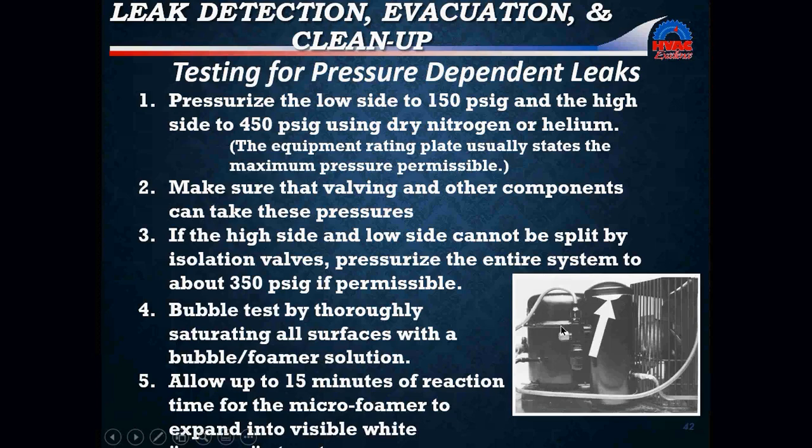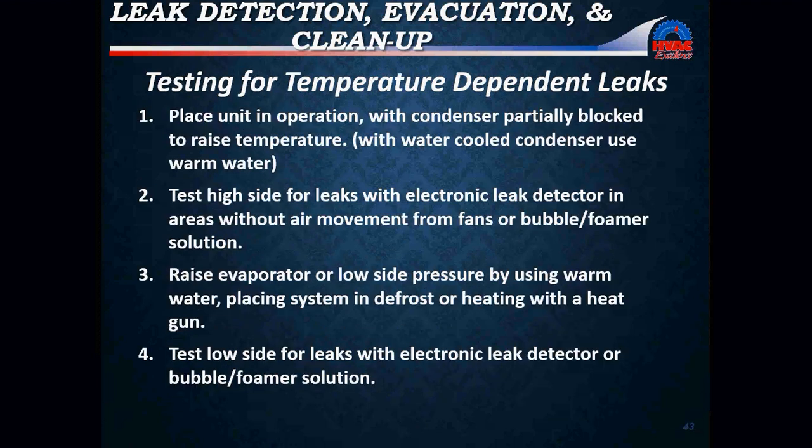Okay, so when we're doing a system-dependent pressure test, start at the compressor. Coat all of the suspected surfaces, including your suction line valves, filter dryers, and other components. With a split system, check the outdoor section and then the indoor section. Do not stop leak checking as soon as a leak is found. There may be more than one, which is kind of common sense.